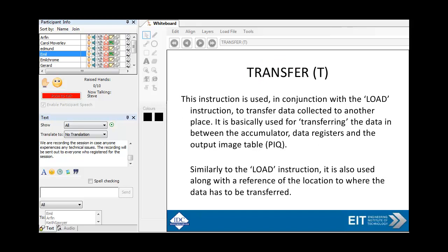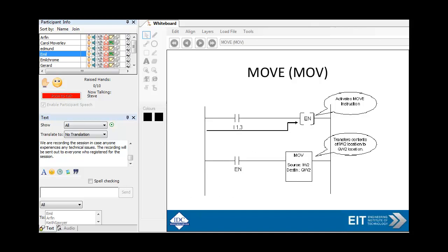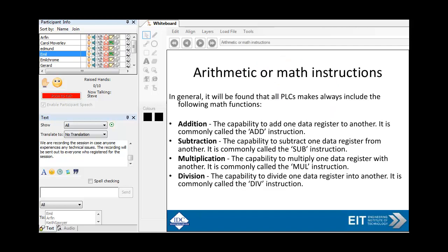In other words, 16-bit registers you can work with as well, so that's quite important. So you may want to move a register. For example, you are measuring the flow rate and you digitize it to 12 bits, 0 to 4095. You may say, if the flow rate is 50%, I want to digitize that value and make a decision. So for example, if the flow goes up to 50%, I want to switch a pump on. So registers are very important, and most analog inputs are 12 bits, which means you can break a signal up into